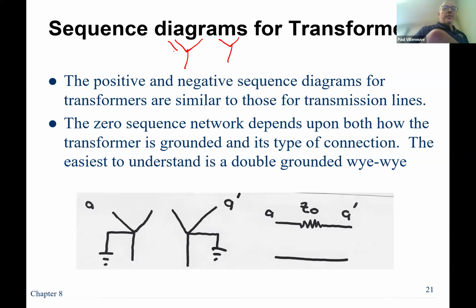So if I've got a current flowing through here, I darn well better have equivalent current to that, right? That's what a transformer does. It's got current going in the primary winding. It uses magnetics and gets the current flowing in the secondary winding. So if I have a balanced set of three-phase phasors, I have 3 currents, all with the same magnitude and offset by 120 degrees. So if there is a neutral connection here or not, it doesn't matter. I couldn't care less if there's a neutral connection.